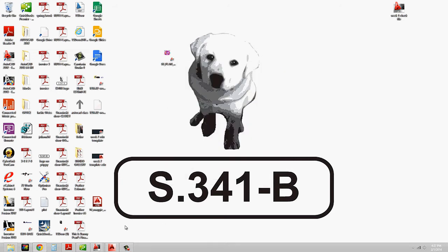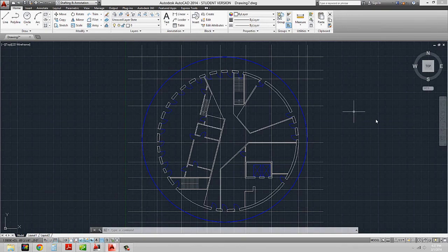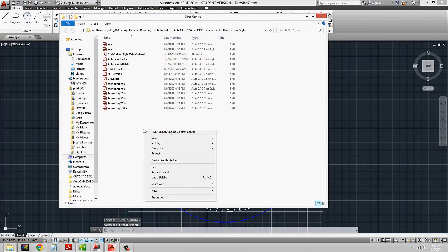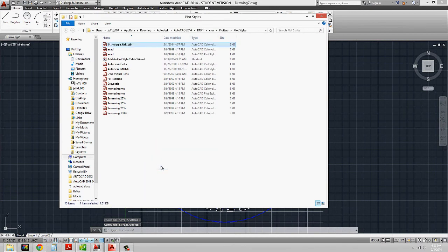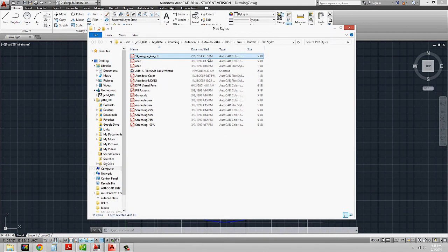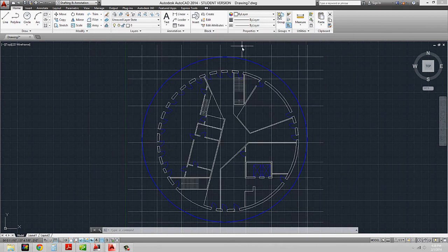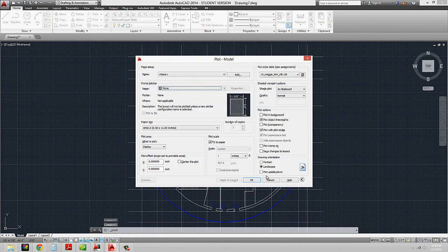but I already did that. I'm going to save and close, and then rather than cutting and pasting it in, I'm going to copy it, and again open up my AutoCAD, type in Styles Manager, and then paste it in, okay? And again, it's a copy, it's not the original, and always keep the most up-to-date within the Styles Manager, so that now I can close it out,